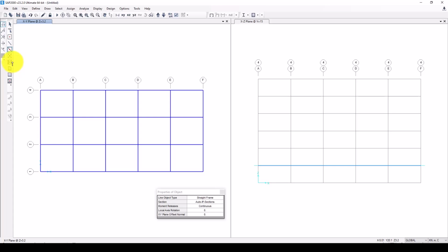And the second one is I want to add some, it's called quick draw secondary beam. We use the same section, and we selected pin, so that means automatically the program will define release moments instead of defining moment, so that one was fixed or continuous. So I'm going to select this one. You can see it's called number of beams, it is 3. We're not expecting 3, we're going to use 2.